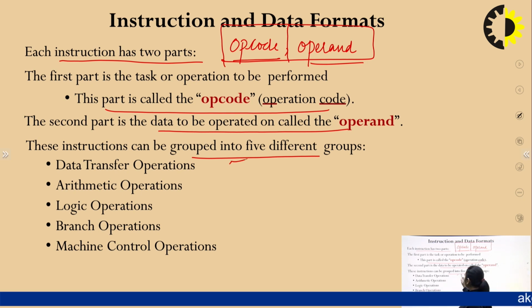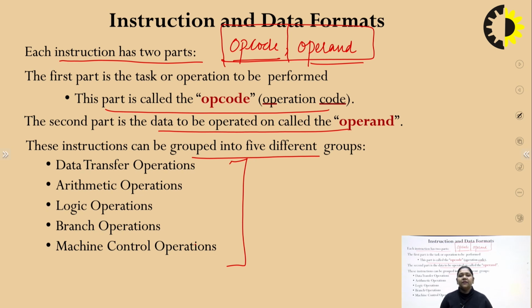Here in 8085 there are a total of 5 types of instructions. First is data transfer, then arithmetic operations, logical operations, branch operations, and machine control operations. Data transfer here signifies that when we have to transfer data from one place to another, that data can be stored in some register, in some memory, or the data can directly be given in the instruction itself. So there are 3 types of instructions here in data transfer. First, the data transfer will be between 2 registers. Second, the data transfer will be between a register and a memory location. And third will be immediate data which will be given.